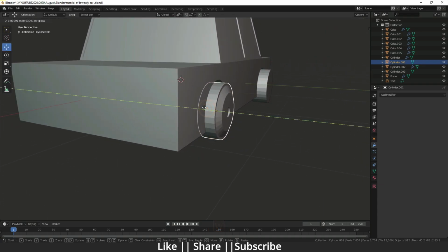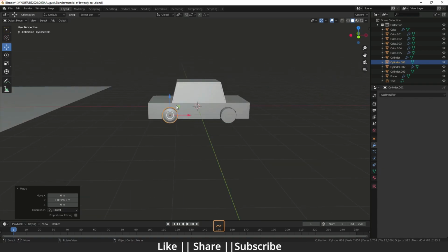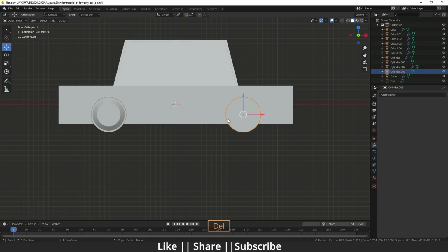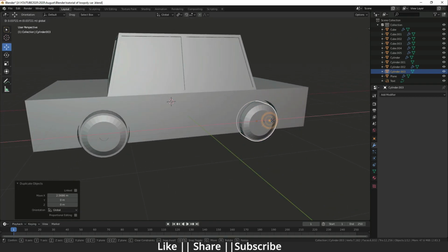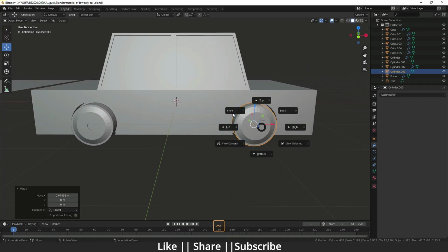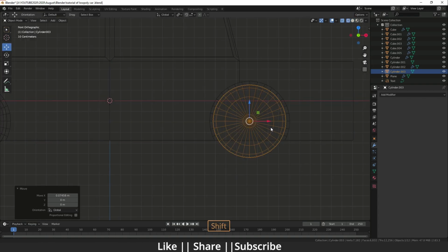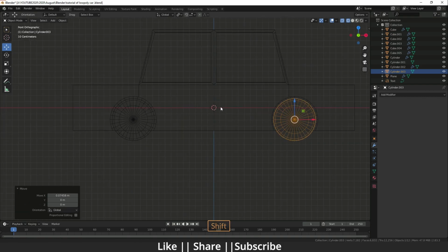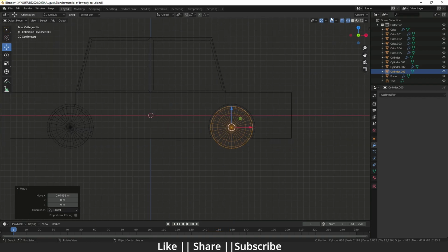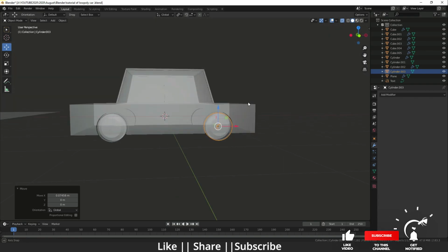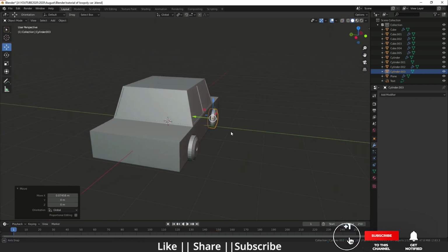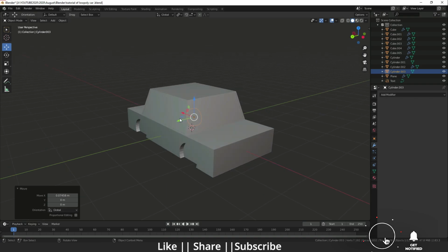Okay, yeah. So now I'm just going to copy this, because I'm not going to make it again. So I just do Shift D and X axis like that. Make sure it's the center of that part. So you can see from here also, and you can see in a wireframe as well. So yeah, it's perfectly aligned. Okay, yeah. So here you can see, so now we need a tire from the other side also.